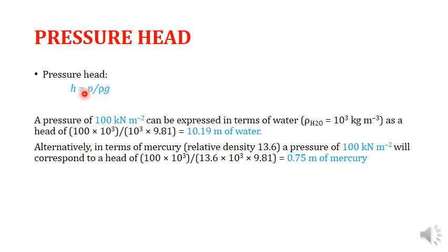The fluid is water over here, its density is standard and g is 9.81. So the head should be 10.19 meter of water.